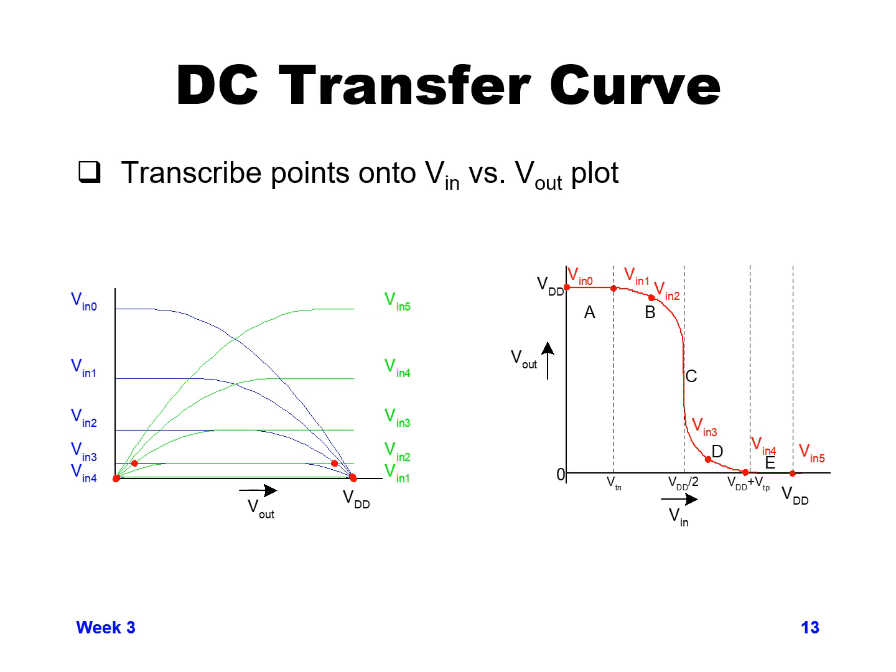Then we're going to get Vout equals half of VCC when Vn equals half VCC, as long as they're completely balanced. If one of them's a little bit stronger than the other, we won't have that switch happen exactly in the middle. But no matter what, when we have something like an inverter, we will get a curve that looks similar to the curve on the right hand side there.